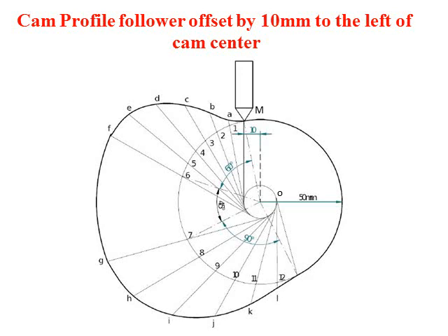Tangent to the offset circle. Make sure that the lines being drawn go beyond the base circle. So after drawing those lines, the same steps that were followed for drawing the cam profile for the inline follower, we will be doing here as well.